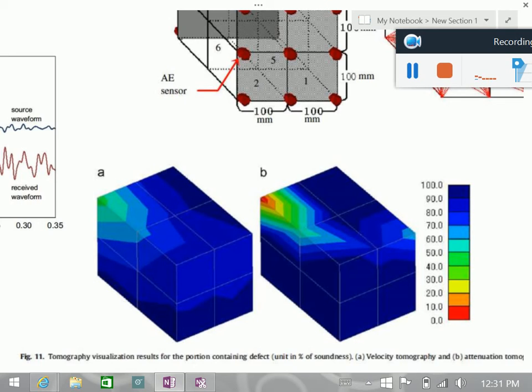Let me give you the answer and let you go. The main reason is that it's very hard to quantify attenuation correctly. First of all, you have to really calibrate all your transducers in a tomography like that so that all of them are comparable. You saw that in your little exam problem, when you compare in contact to the sample, you have to take into account all different things inside each transducer, all the gains and so on.